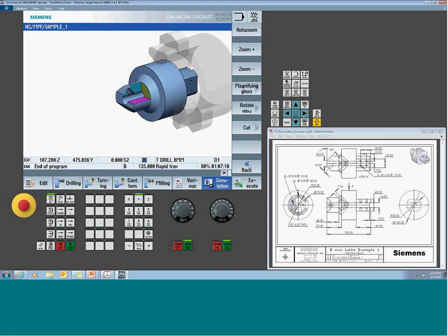All right, so job done. I can activate the cut for now. The final operation, looking at the print, is some holes, kind of like a bolt hole routine on the inclined plane, so it's different. If I was to use a standard bolt hole on this surface, it would be working around the surface, but we do have an option to rotate around. So I can create a plane and rotate it around.